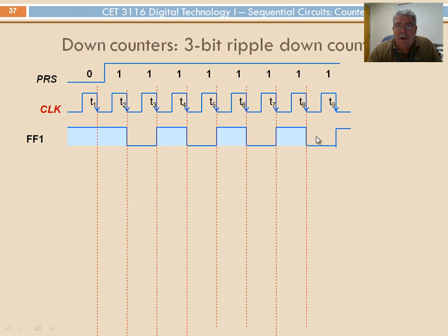This is the rightmost column of the truth table. It toggles every row, 0, 1, 0, 1. No difference at all. Now let's look at the complemented output, which is going to be the clock for the next flip-flop. Of course, it is the inverse of this signal.